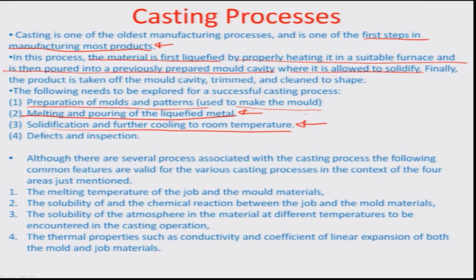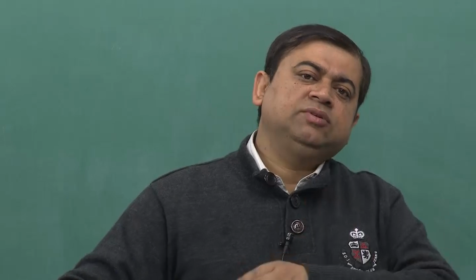One of the reasons why this is important is that we assume that most of the metal goes into the mold from the gate region as liquid metal. Once the liquid is stationed inside the mold, and you have obtained an indication from the other side, which is also known as the riser side, that the metal has fully filled the cavity, there is going to be heat transfer of this metal to the casting walls. Pressure die casting, where a metal mold is basically used for filling of the metal.